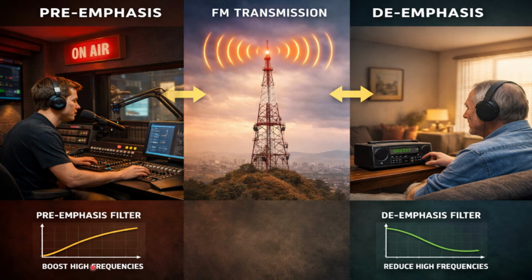The pre-emphasis circuit boosts the high frequencies, and the de-emphasis circuit suppresses them, meaning the transfer functions are the reverse of each other. This is the relation we have to understand: pre-emphasis and de-emphasis are just reverse, both having reverse transfer functions. So we'll use this technique.